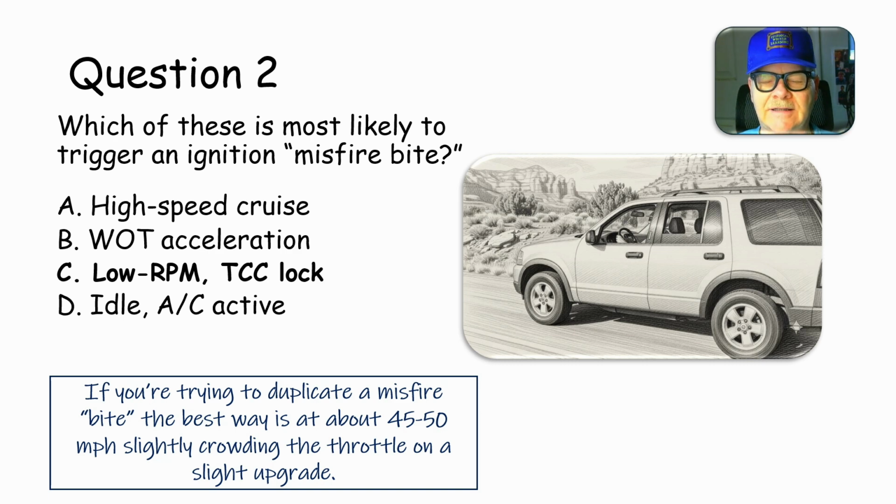I thought it was crazy that he drove a perfectly restored '65 Mustang like that, but anyway, just for the sake of argument, before I did anything else to it, I hooked that Interrogator up. It didn't have a scope, but it would give you numbers on the screen about all your firing. I saw that one of the plugs was firing at 20,000 volts, and the rest of them were firing a whole lot lower. So I found it that way. But that was one of the crazy ones.